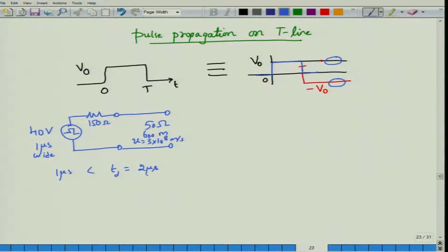So, we consider the same parameters as in the last module, except that now the voltage source has become a pulse. We will consider a resistive termination with a resistance of 16.7 ohm. Obviously, this value of 16.7 ohm was picked for mathematical convenience. Why? Because it makes gamma L equal to plus half and gamma G would also be equal to half. You can calculate this and verify that this would indeed be the case. So, this is just to make the numbers look better.